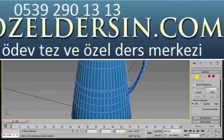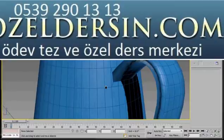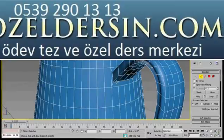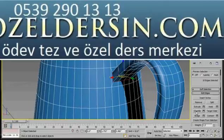I'm just going to zoom in to have a closer look. We also need to chamfer the edges around the handle. We'll select one of the bottom edges here, press Loop, then we're going to scroll down and click on the small settings icon for Chamfer. And here we're going to type in 0.03, then press OK.